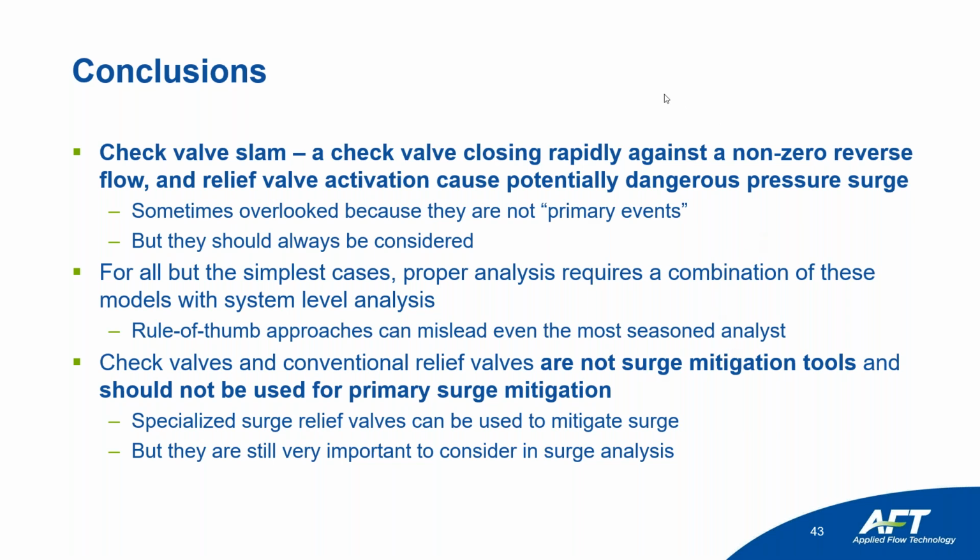All right, and I see a couple of questions from earlier on. One is just, why are we trying to avoid surge? What is the detrimental effect this pressure has on the system? Maybe from closing a valve like a check valve too quickly. And the simple answer is, if the pressure is high enough, it can burst pipes, it can damage equipment, it can knock pipes off of supports, things like that.